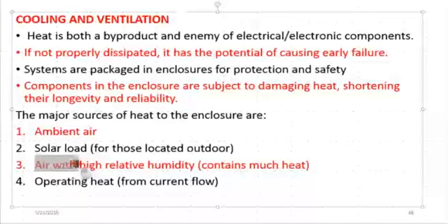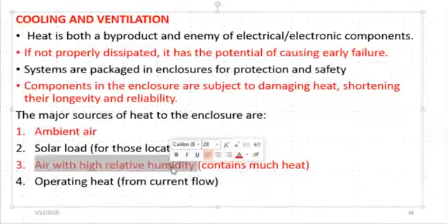And the air that has high relative humidity, that is moisture content. You know, it is the heat that changes the water molecules into vapor, meaning it is that heat that is retaining them in the vapor stage. When they enter a compartment, there is every tendency that the heat in the water vapor will go out and the moisture will now condense into liquid.